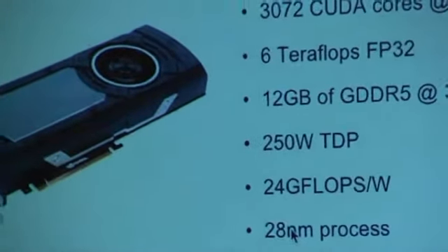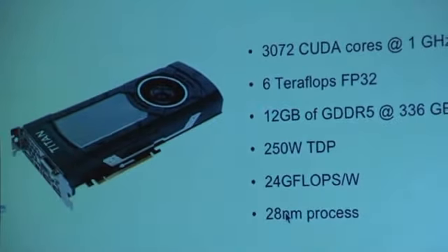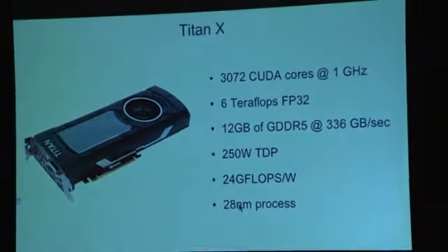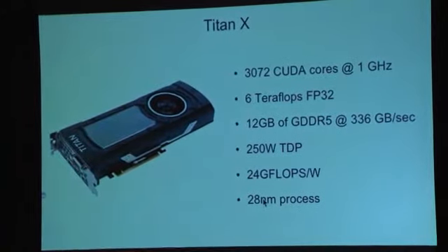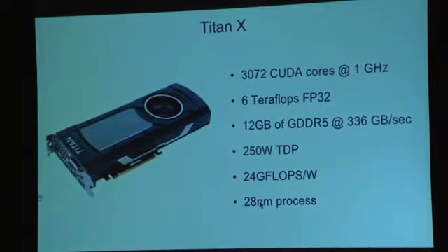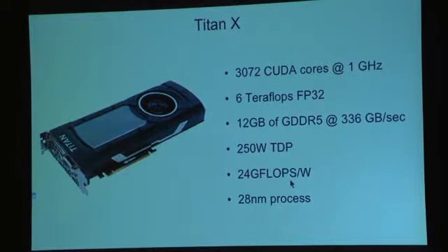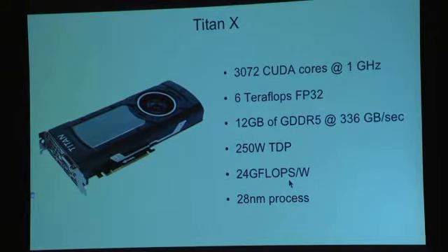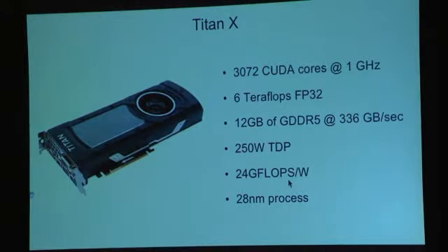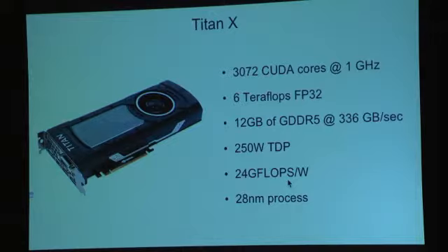The Maxwell generation GPUs like the Titan X and the M40 are in the same process. They are almost exactly twice the performance at the same power level, twice the performance per watt with no process change. So Moore's law, the process isn't giving us any more performance or performance per watt, but with GPUs we're able to double our performance per watt over a generation within the same process, and that's why GPUs are able to do so well at this.